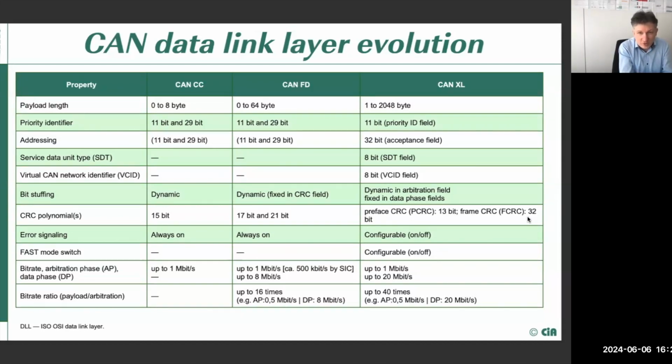So payload, surely, with overhead, you could put the whole Ethernet frame inside. Priority identifier: even classic CAN has it, and could use 29 bits for large trucks in J1939 systems. In CAN XL, people said no, we do not need this big an identifier, we do not use the priority identifier for anything else except the priority of the message itself. That will be sufficient. Regarding addressing, it was not available, but could be done, and it was also done, especially by us in CANopen and CANopen FD.